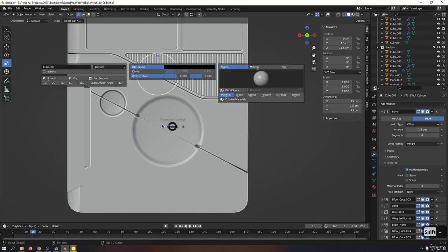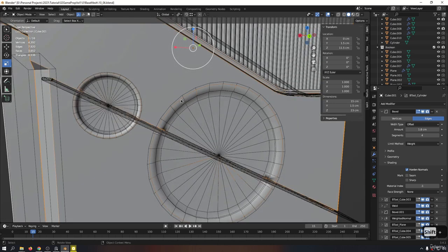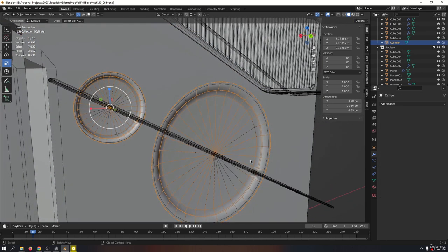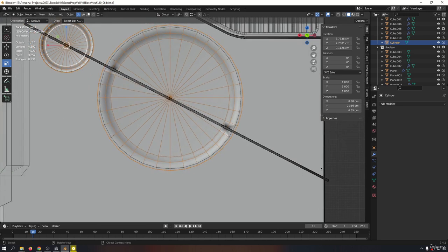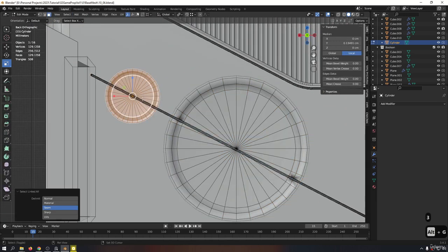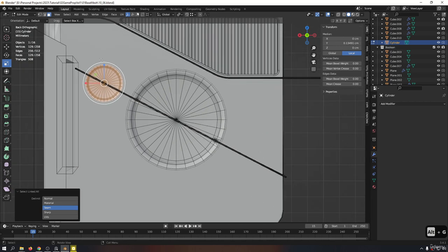And because we're doing that in the edit mode, all of the modifiers that we have applied on this and all of the details are gonna be captured, because this is a Boolean piece and everything that we add to this is gonna be applied to the geometry. Again, I'm selecting this, Alt and G to select all of it.